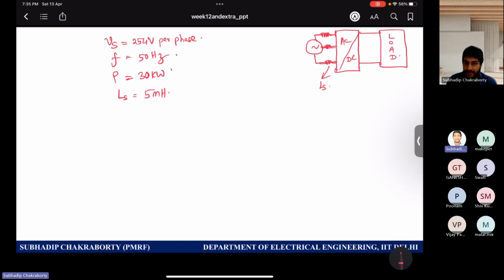I told you in the previous week that in an inverter, seen from the DC side to the AC side, it acts as a, can anyone remember? Right, it acts as a buck converter. Seen from the AC to the DC side, it acts as a boost converter, right? This has many interpretations, like the synchronous machine you must have seen. Two nodes, this side voltage is different, this side voltage is different, so power transfer can happen. An inverter can also be modeled as a synchronous machine.